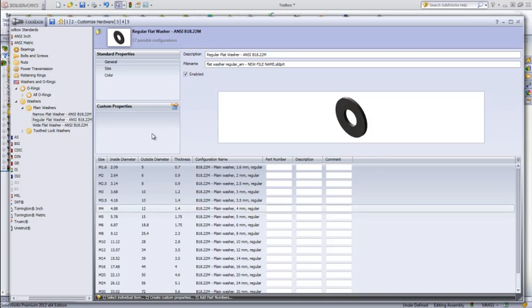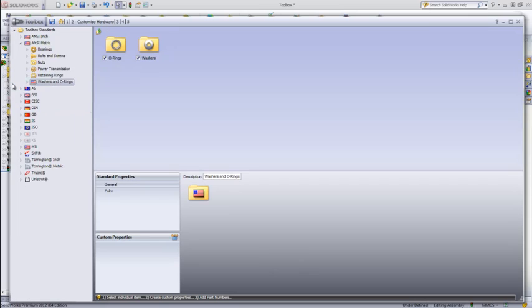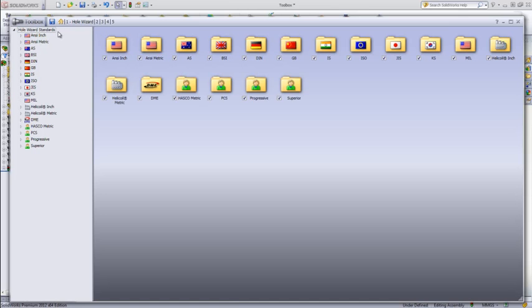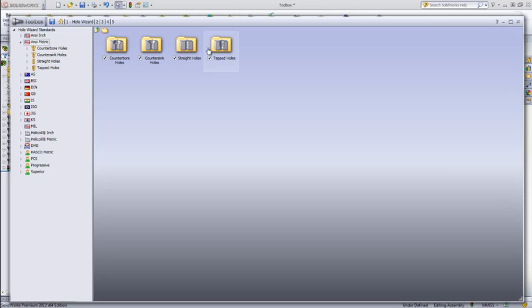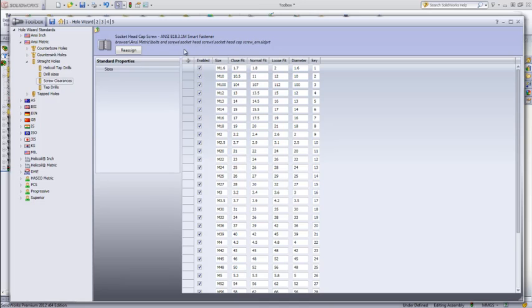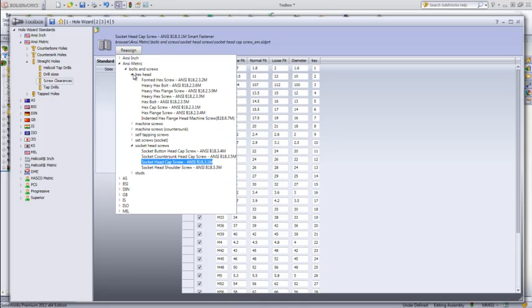The SolidWorks Hole Wizard database has been separated out into its own category within the Toolbox Settings application. You can now pick which sizes and standards you wish to be available, along with which smart fastener you want to populate for each hole type. A more granular selection of smart fasteners also allows you to automate the addition of fasteners for your holes that match your own company standards without any compromise.